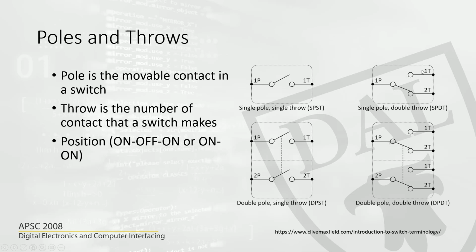Sometimes you will have 2 circuits. This is sometimes called a three-way switch as well because it has three contacts. Let's say I have power running through this. I have one light bulb connected to one terminal and another light bulb connected to the other terminal. When I put it in one position, one bulb will be turned on, but when I move it to the other position, the other light bulb turns on. So there are things like that.